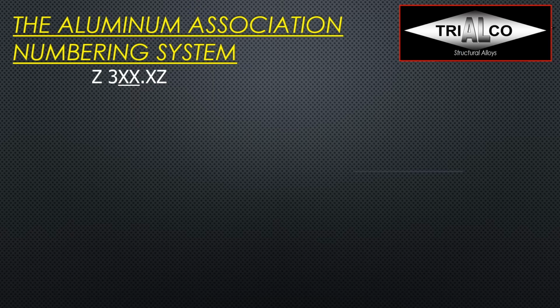And I think a lot of you are familiar. There are two different numbering systems. One is the wrought alloys, and they are usually 4 digits. So you might see a 6061 alloy or a 6082 alloy. And then you have the casting numbering system, and that's totally different. So we have 3 digits, sometimes a letter in front of it, and sometimes then something else behind it.